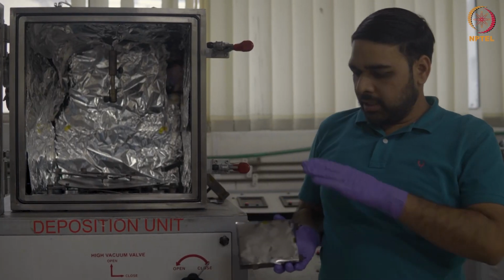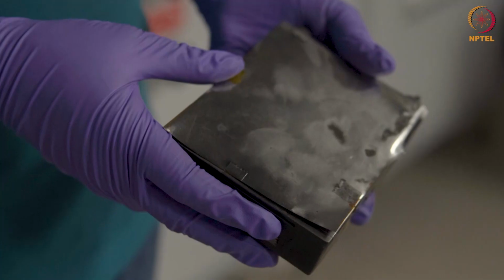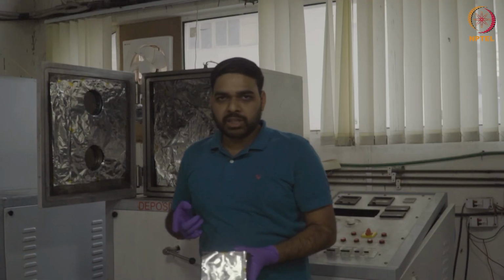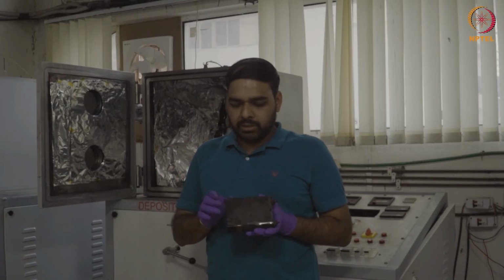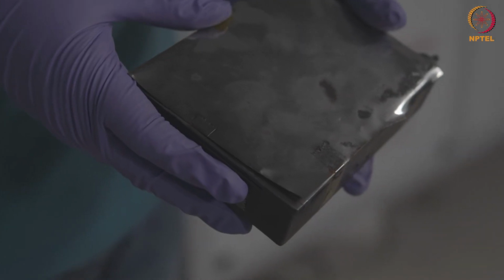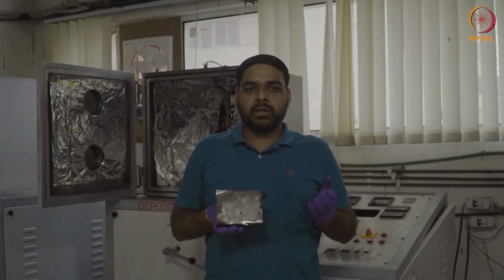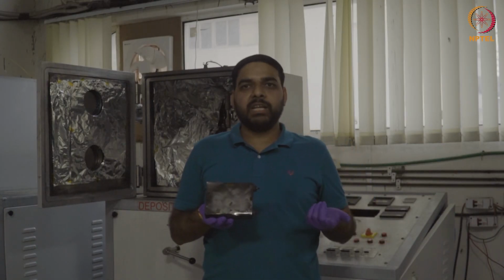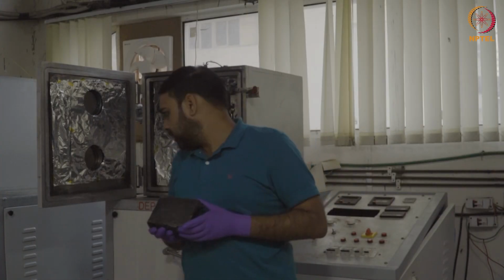Post deposition, our film will be deposited on a Kapton polyimide substrate, and it will look like a silverish colored NiTi film. This structure is a double layer structure where nickel titanium is deposited on the Kapton polyimide substrate, and we term it as bimorph. Why? Because it has two active materials. One is Kapton polyimide and another one is nickel titanium, both taking part in actuation cycles, one in the cooling cycle and another one in the heating cycle.